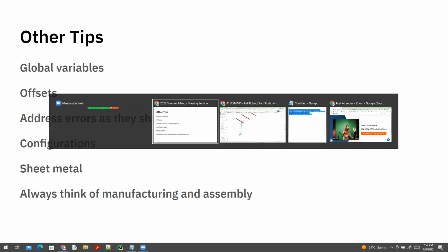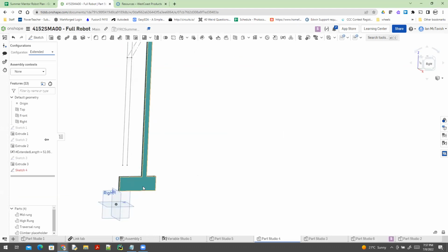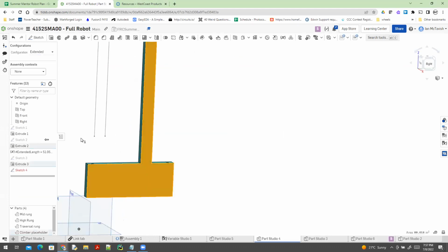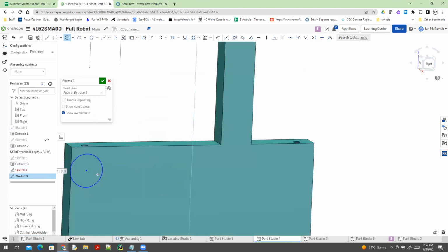But the other thing I mentioned earlier on, I'm just going to demonstrate with this sketch here. Going to make a couple. So I've just added a sketch to this side. 1364 we found is a perfect size for a drill bit for 10-32 screws. So I'll mention 5mm is also a good option if you can get it. Yep.